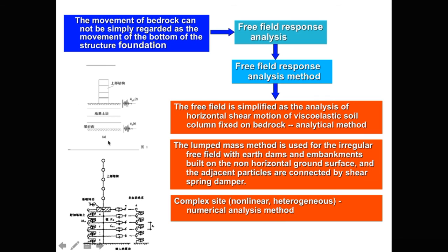And let's see the left picture I already introduced. The upper structure and site on the layered soil and above the bedrock. In fact, in bedrock we can determine the earthquake acceleration time history, and we can do the free field analysis to get the acceleration time history on the ground surface.